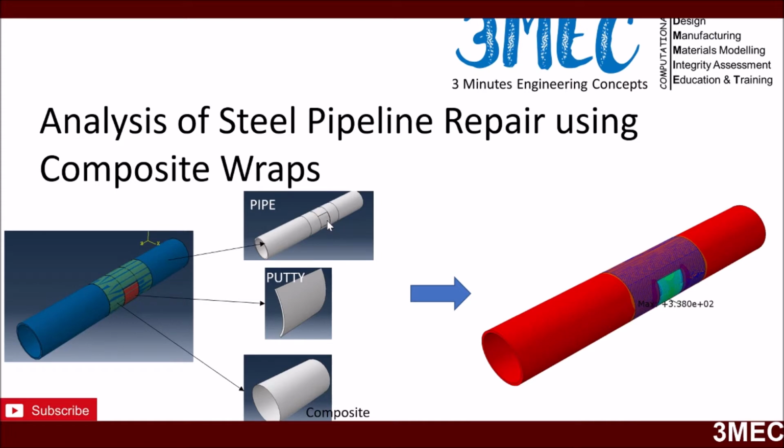What you do in real life is you put some kind of adhesive. In this case they use putty during the experiments, and then they wrap composite layers around it, as you see here. So this is the composite layer, and then this is the final assembly. And they wanted to see, okay, before the composite repair and having a composite wrap onto it, what was the burst pressure. So they measured that during the experiments, and then after putting everything, they again tried to find out what is the improvement in the test.